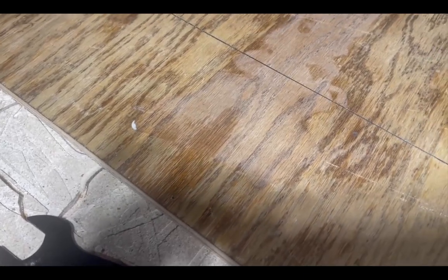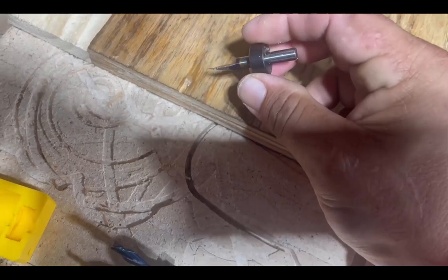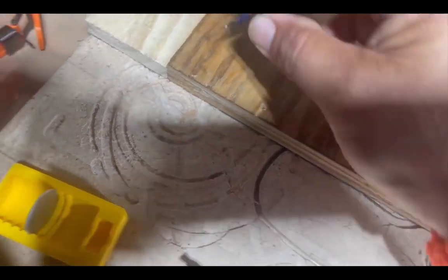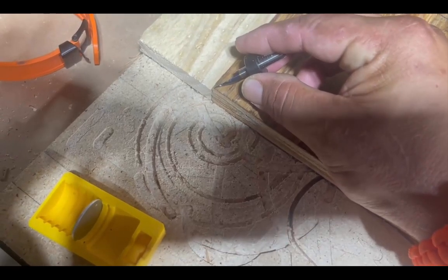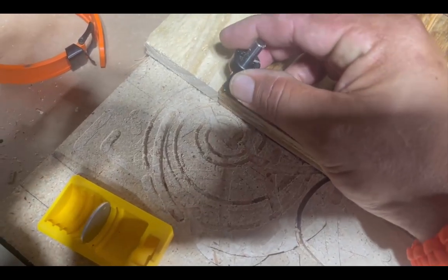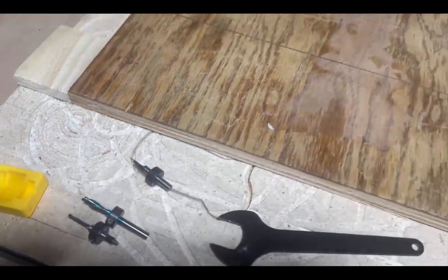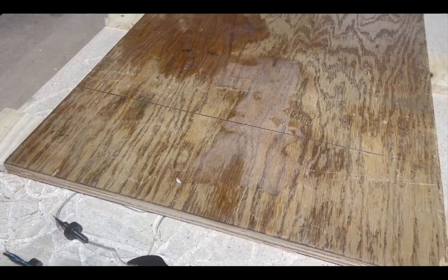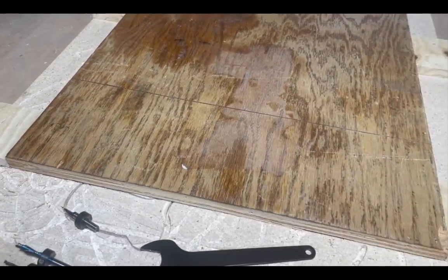the first portion cut. So what I'm going to do to set my zero, I am going to take my 60 degree here, and because it has a fine point, I can put it right there on that corner as my start point for my first part of my cut. So I'm going to go ahead and get that done. Get my zero set for my first cut and go ahead and start cutting.